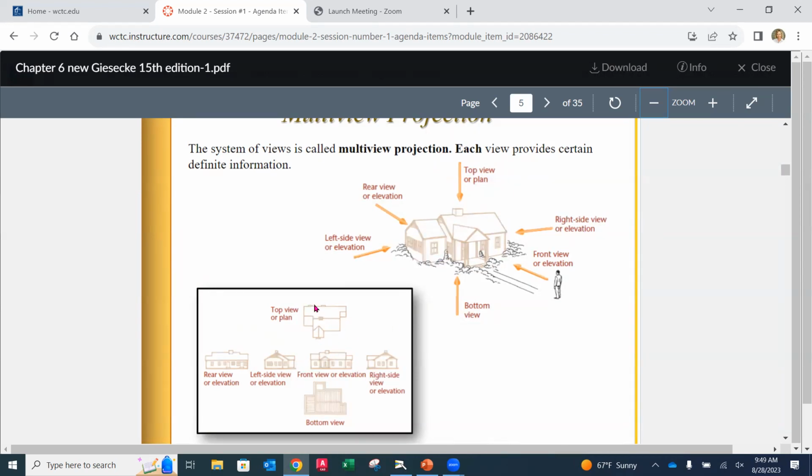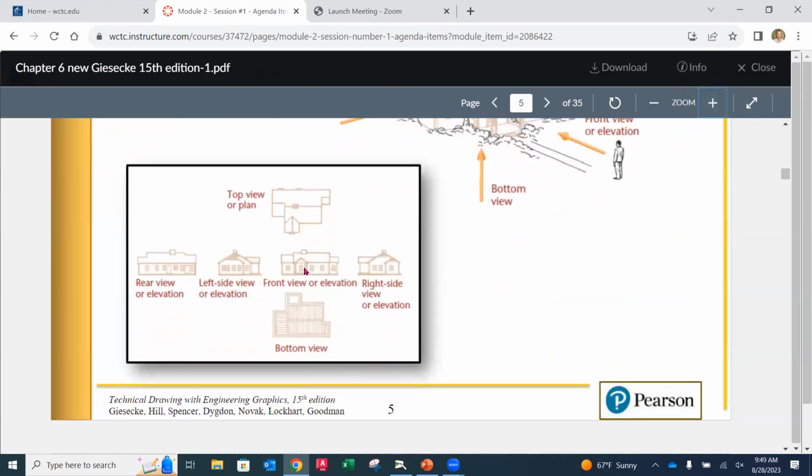As we look at the drawing, I'm gonna zoom in here, make this a little bit bigger. As we look at this drawing, notice something, that in our front view, the ground level, or if you would, the bottom of the house that we see in this view, there's probably basement down below. But this is all in line across each one of the views that we create. Do you see that? That's common. The height additionally is at the very top of that chimney. If I take a straight line, I go over, those are all in line with one another.